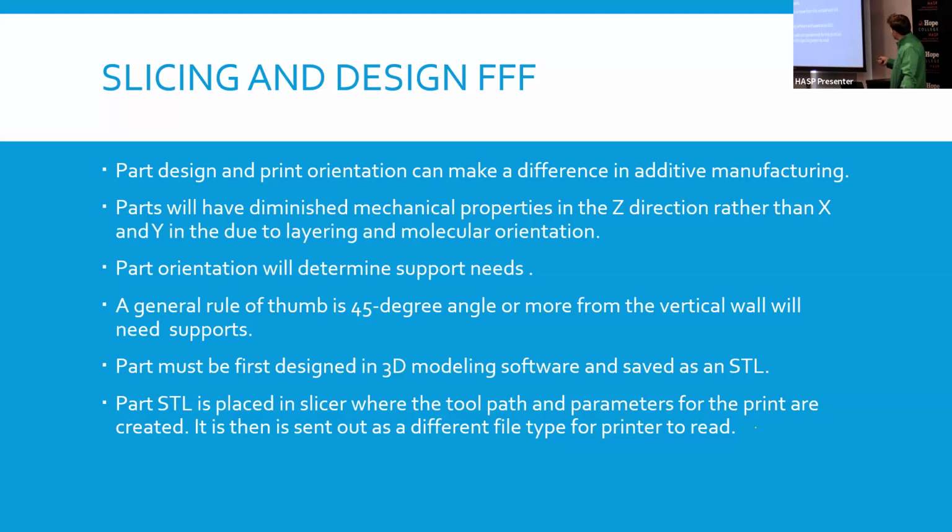Speaking of mechanical properties, parts will have diminished mechanical properties in the Z direction rather than the X and Y due to layering and molecular orientation. So this doesn't really take place in powder beds, but it does take place in extrusion. So holding up this part, if you saw, you got this big line right here.